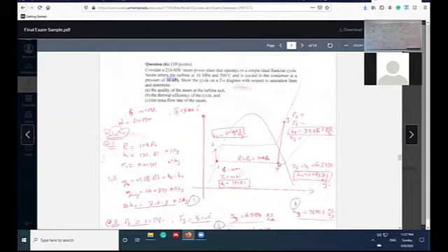It is the same as state 4. State 4 can be here, state 4 can be here. But he said find the quality. It means it is here, saturated mixture. So state 1 is totally defined. I can get anything. The most important thing here is H's. Always box the H's. Also, at state 1, we can get V1, which is the same as V2.